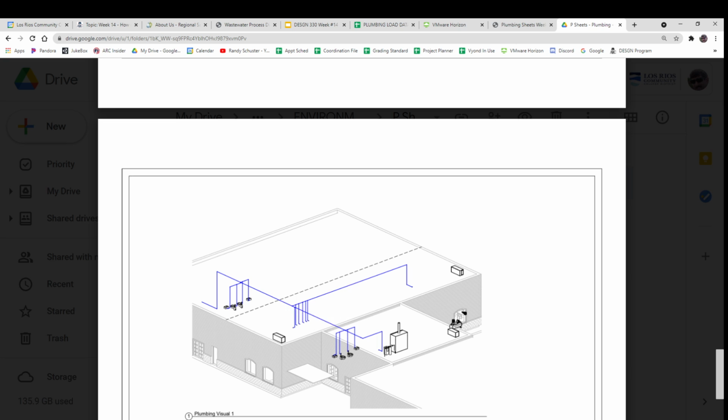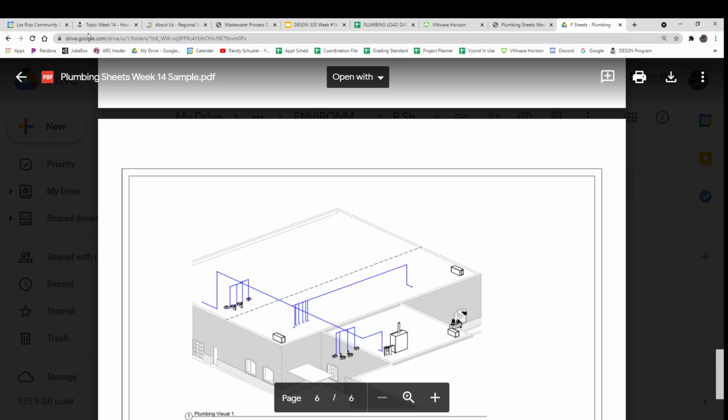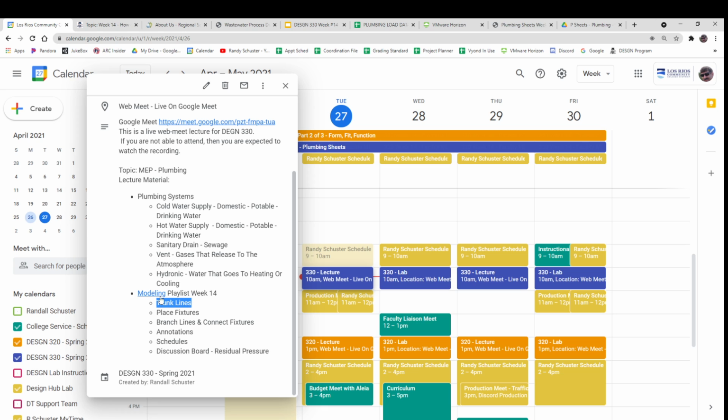Usually you really talk about the trunks and the branches when you're doing all of your estimating. So that's why I said anything over 5 feet long we'll consider as being a reasonable thing. So once you've got your trunk lines, then you place your fixtures. Those are the things that take water. Toilets, lavatories. And then we put in a thing called a hose bib.